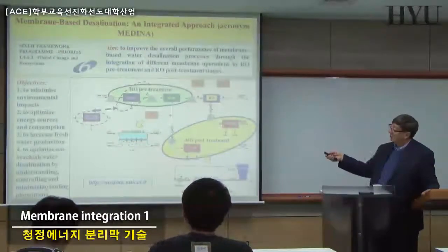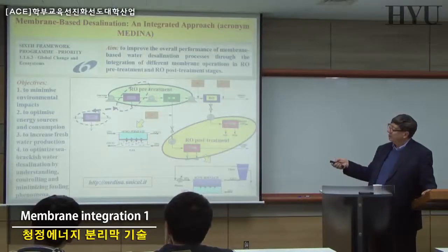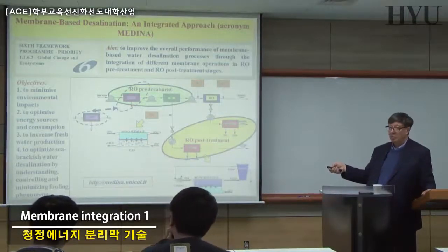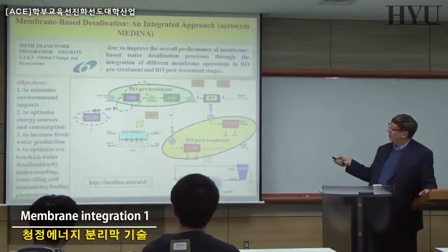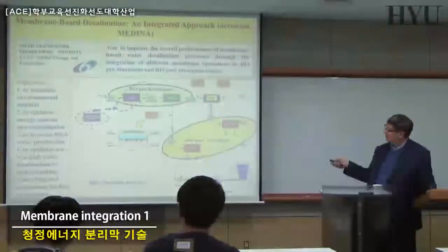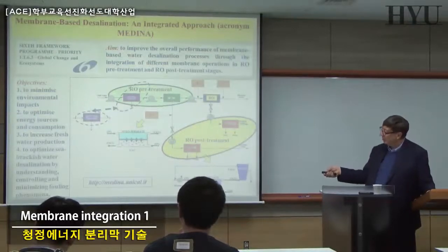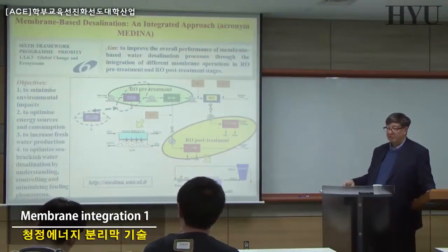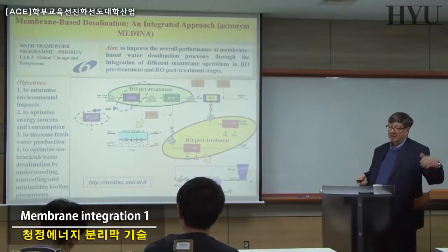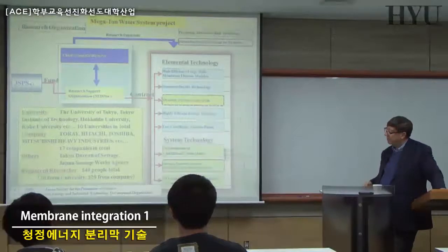And as you can also realize, what we call zero liquid discharge works in this way, because basically you enter here with seawater or brackish water, and you go out with the salted water, but all the rest, there is no more brine disposal, because using membrane distillation and membrane crystallizer you have just salt crystals coming out of the system. Fresh water on one side and solid material in the form of advanced crystals.